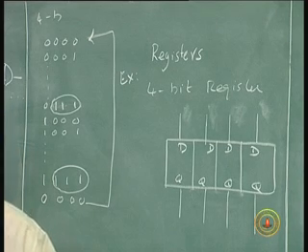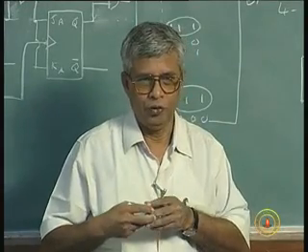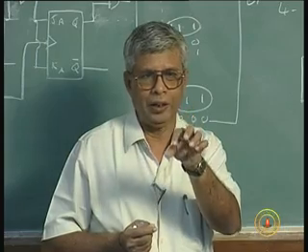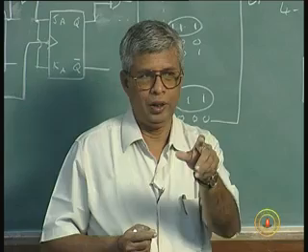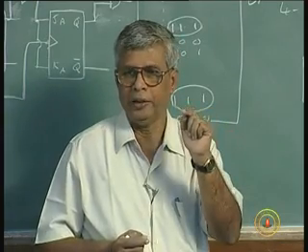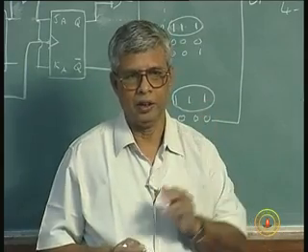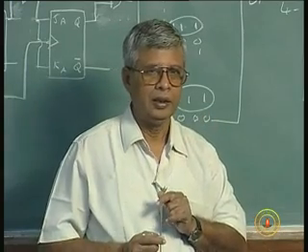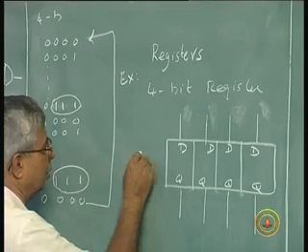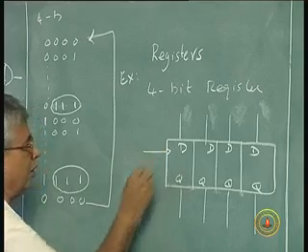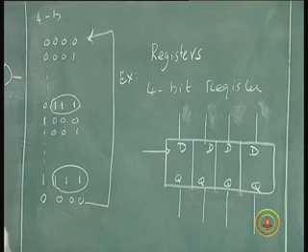Normally, these flip flops can be controlled by a single clock. Internally, that is connected, of course. As I said, externally, when you are looking at a device with 4 bits, as a user, you have only one clock to connect, one power supply to connect. So, all these flip flops need VCC and ground, or VDD and ground, or whatever is the nomenclature for the supply voltage. All those things we are not showing. Similarly, when we say one clock pulse, can be edge triggered, positive or negative, whatever, it does not mean that these flip flops do not require clock. It is all internally connected. The clock is connected like this.